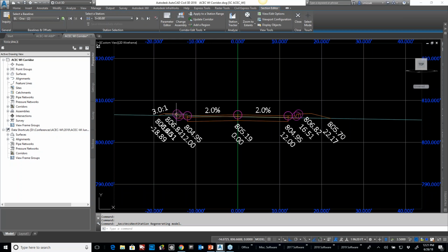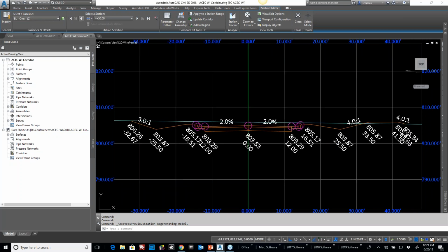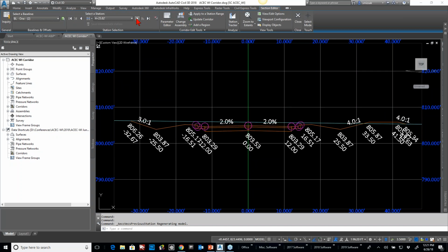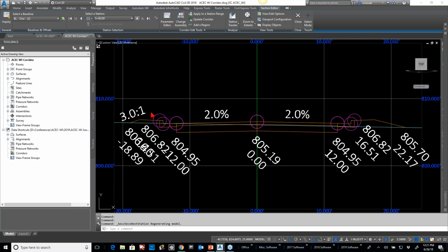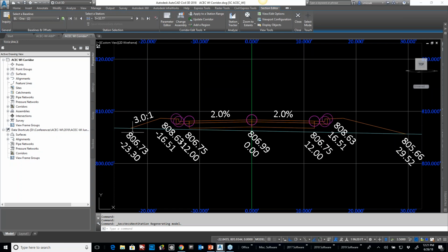my attachment point in here. So even though I'm above here and I'm below here, these values are set based off of the attachment point on whether it's a ditch, or if it's a ditch with berm, or if I'm in just a flat out fill situation. So when I get completely above, now that my attachment point is above, now I go to a fill. So depending on the terrain and where I attach is going to make that distinction.